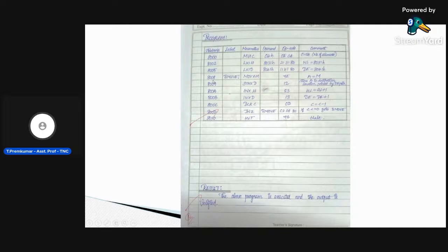There we're going to move the data which is in the memory location HL to the accumulator. After moving that memory location content to the accumulator, the next instruction we have is STAX. This takes the data from the memory location addressed by the HL register pair, which has been moved to the accumulator, and stores that accumulator data to the memory location addressed by the DE register pair. That is STAX.